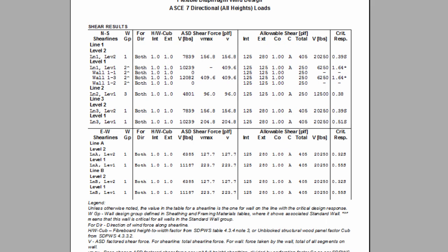The perforation factor is a factor that reduces the nominal unit shear capacity of the shear wall based on the sheathing area ratio and the ratio of the total length of the shear wall to the sum of the individual perforated segments contributing to the shear resistance. The wall capacity is determined based on the lowest perforation factor. The total unit shear resistance of the shear wall, total, is determined by applying the SDPWS sheathing combination rule.